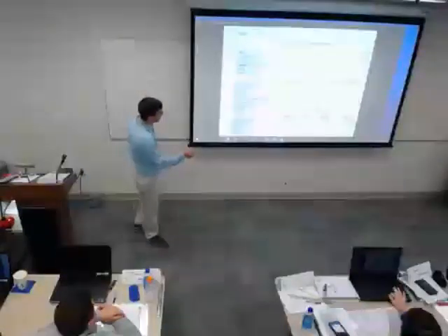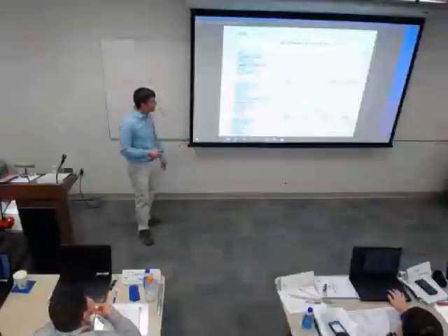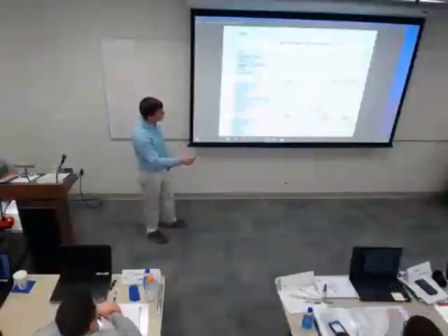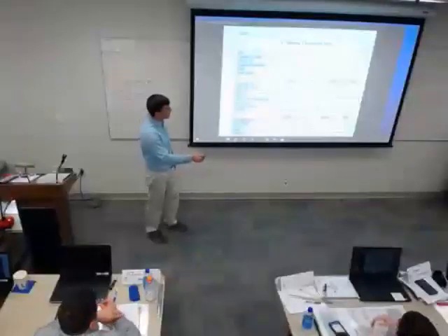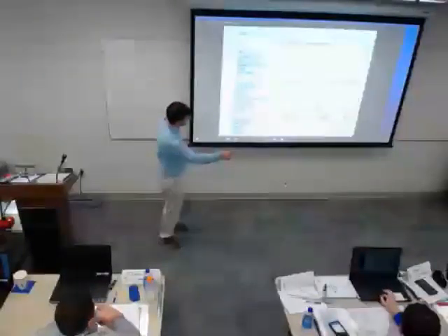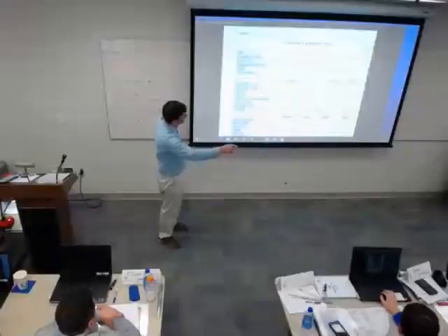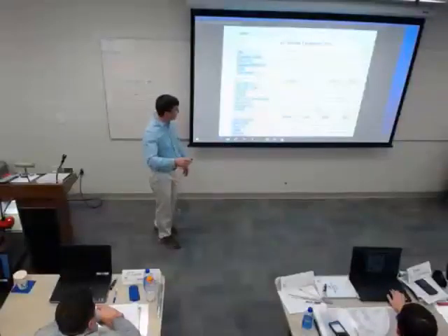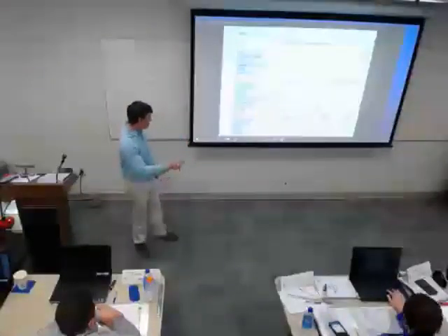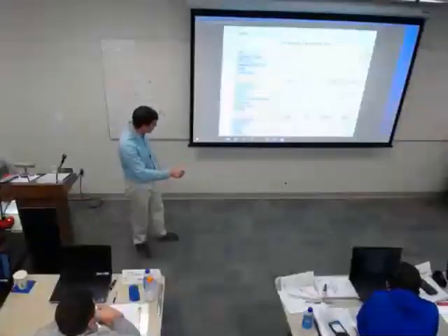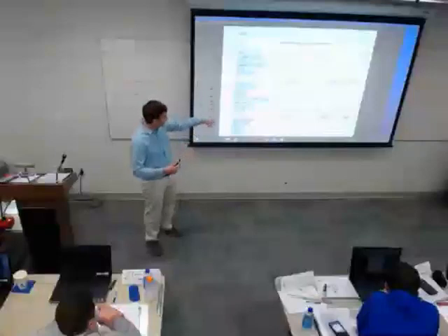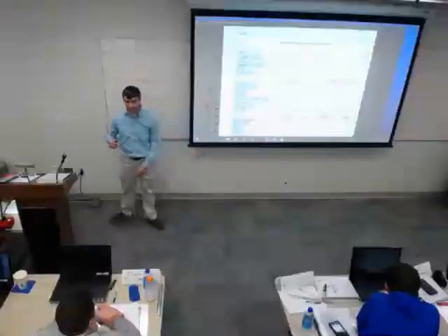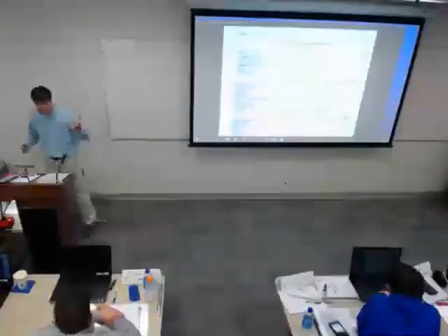Typically, the main thing we're talking about is cubic feet per minute. We're going to come in and fill out from our design plans: how much am I supposed to have? How much do I have? This is actually for 2 pieces of equipment. This would be for 1 piece, and this would be for another piece if I had 2 fans. We're going to talk about all these numbers as we go through the rest of this lecture. But the point being, I want this thing filled out by my TAB guy. I'm going to show you the things that he's supposed to do to get this filled out.